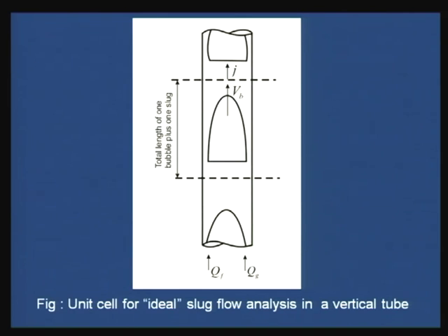For turbulent liquid slugs, we can have a flat velocity profile, but otherwise we will be having some sort of a velocity profile, and due to the existence of this velocity profile, since the bubble tip is directed at the center of the tube, there will be a tendency of this bubble tip to rise with respect to the center line velocity of the liquid slug rather than the average volumetric flux of the liquid at the cross section ahead of the bubble. Correct?